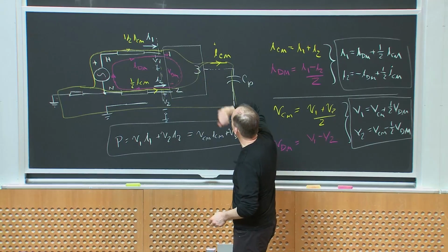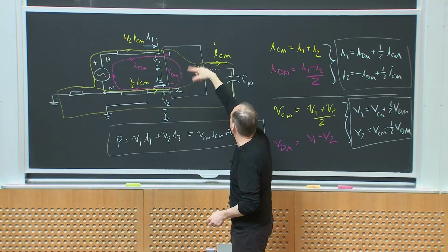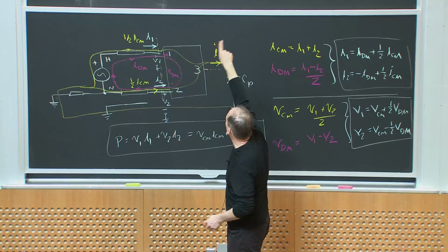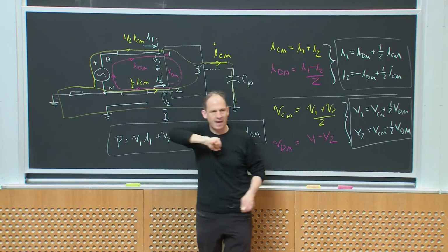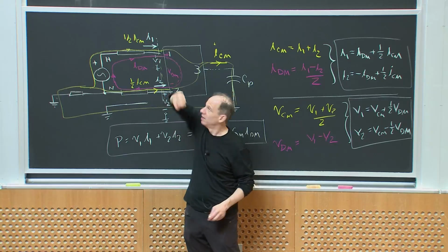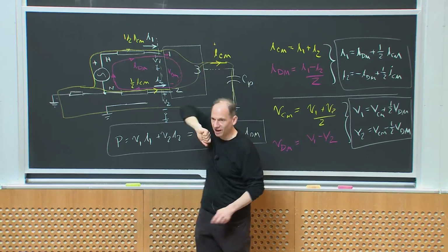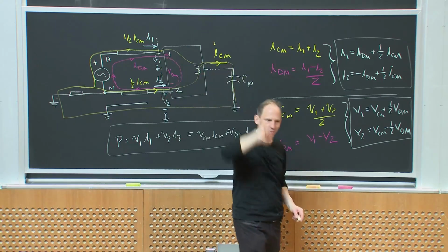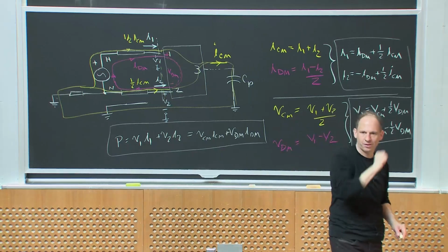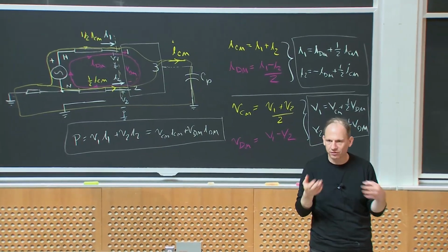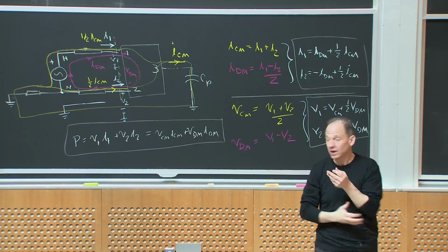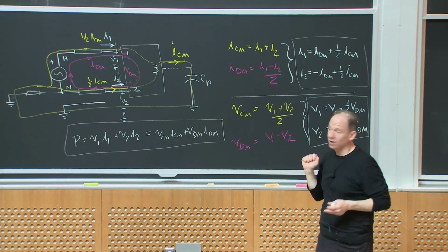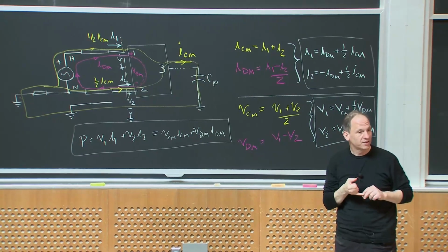And keep in mind, we're going to have to put some kind of filtering to deal with the fact that I can't allow lots of high frequency currents through this path, right? So I can't just do what I did before and have a single-ended kind of filter that filters one path. I'm going to have to do something that filters both leads going to my converter, okay?